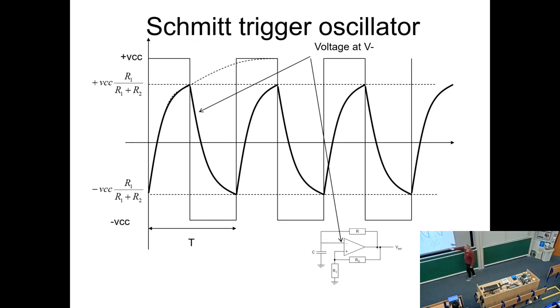So the output, Vout, is this black square wave, which has a 50% duty cycle, so it's equally high and equally low, and the frequency of it is controlled by the values we've put into these components here. So you can make an oscillator for driving a clock. Clocks drive digital circuits. All synchronous digital circuits require a clock. There's an easy way to make one. Isn't that interesting?